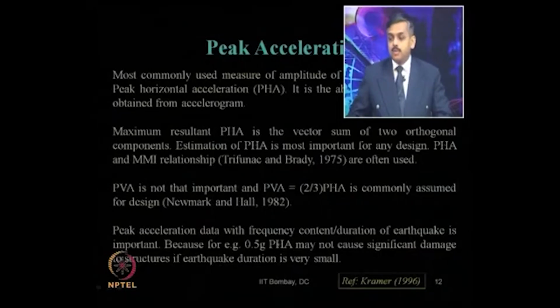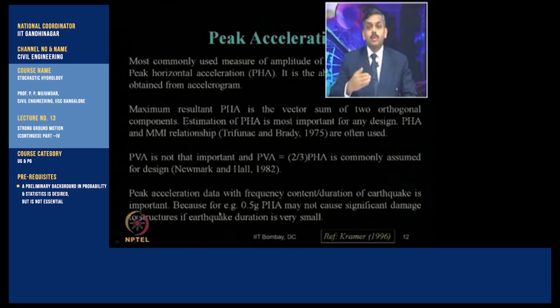Such a high value of PHA, 0.5 g, if it occurs for a very small duration, say 1 or 2 seconds, may not be very damaging, because your structure will not get sufficient time to respond to that.